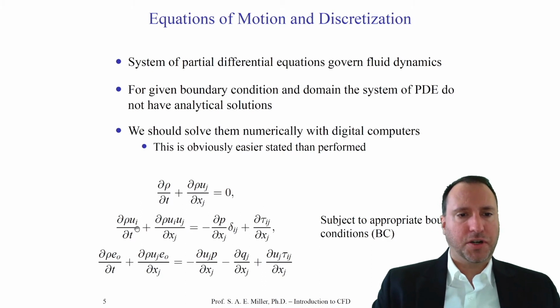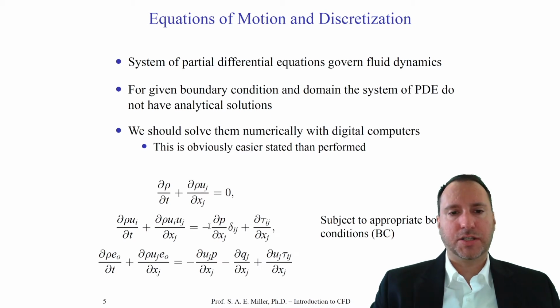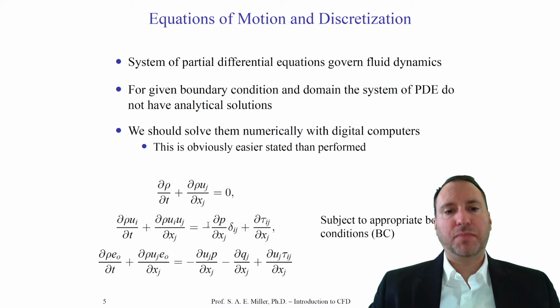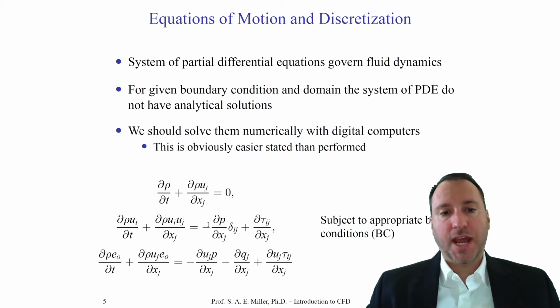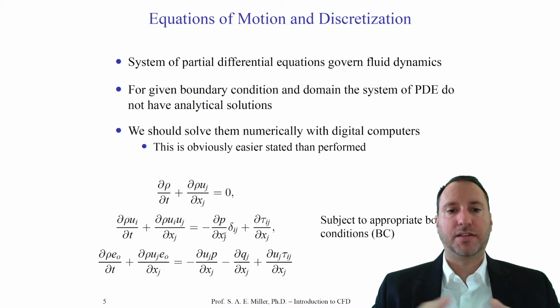So the first term only has a single index i, so let us set that to 1. And we set i equals 1 in all the other terms. So for example, the third term, the pressure gradient term, would be negative partial p partial x1 delta 1j. Now in this term, you see that there's two j's. So I would sum over them for the i equals 1 equation. This is the x direction conservation of momentum equation.